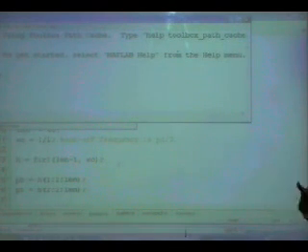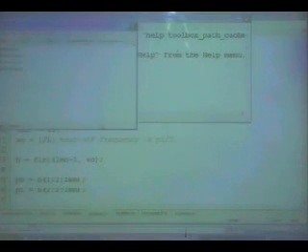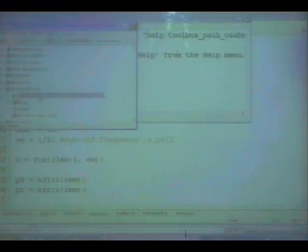But knowing this, the MATLAB toolbox is a very powerful tool. So you really need not experiment with the design yourself. Don't try to design a Butterworth filter and all that, because knowing all the trade-offs, go here, invoke this, whether you intend to map it on FPGA or on a DSP processor or just on a general purpose processor, just use the MATLAB toolbox, design it and export it to a header file or a C file. So the important thing is learning the tool.